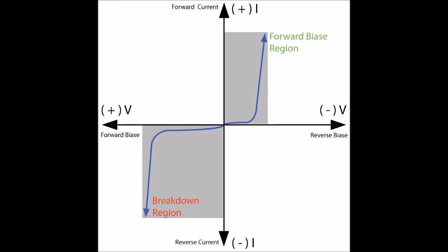The Zener diode has a well-defined low reverse breakdown voltage by design. A typical value for the breakdown voltage is, for instance, 6.2 volts. This means that the voltage at the cathode can never be more than 6.2 volts higher than the voltage at the anode, because the diode will break down and therefore conduct if the voltage gets any higher. This effectively limits the voltage across the diode.